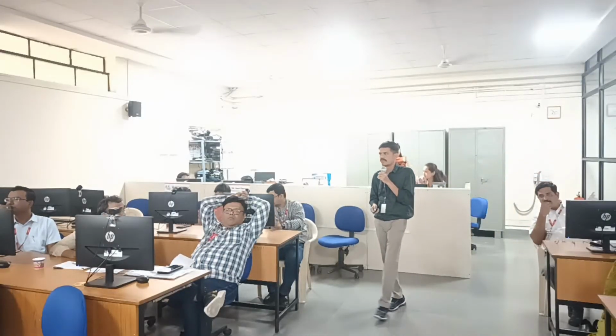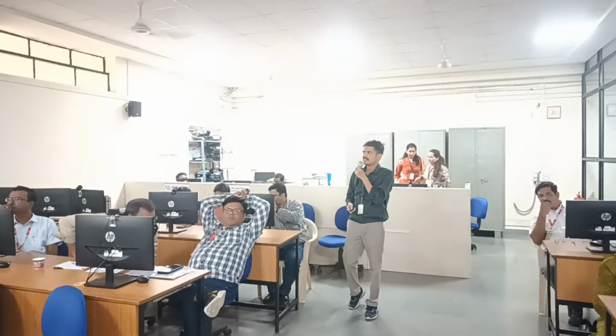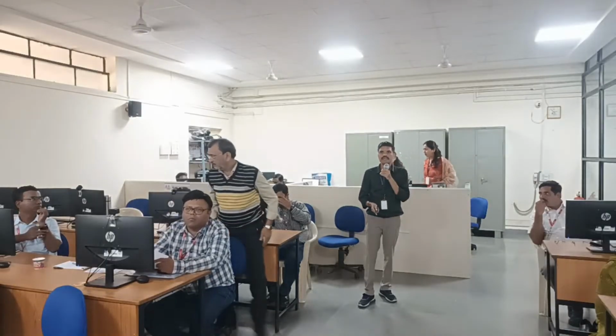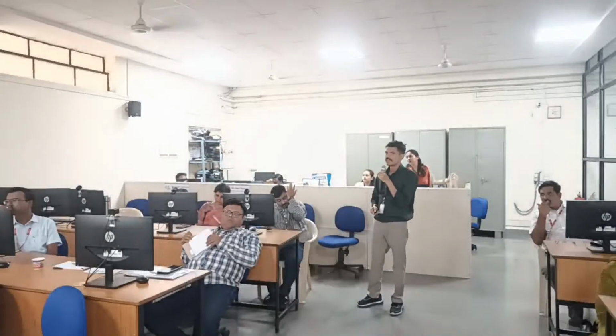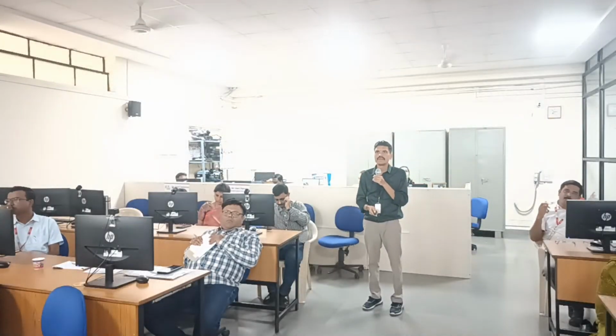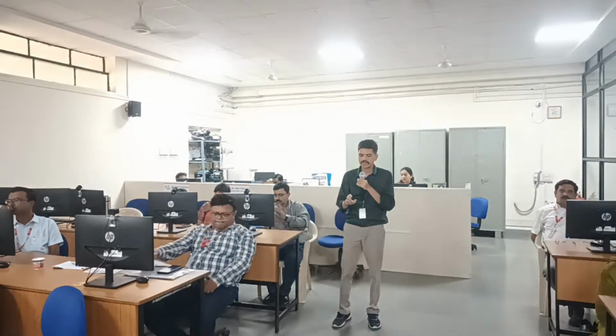You may ask the question, why? The answer is the band gap. The band gap between the valence band and conduction band is very high for the gallium nitride semiconductor. Hence, they can operate at very high voltage and can produce very high power, so they are suitable for very high output power. Gallium arsenide is most suitable for LNAs, and gallium nitride is most suitable for power amplifiers.